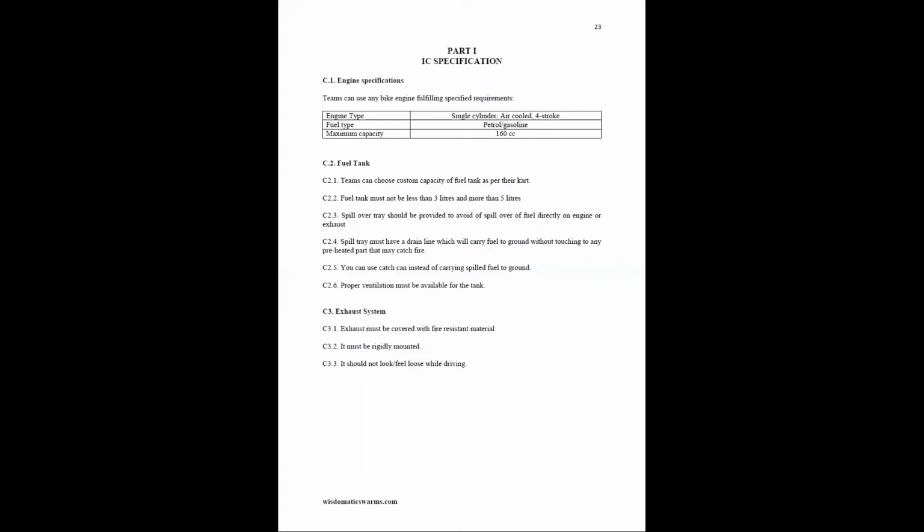Your exhaust must be covered with heat resistant material. It should be rigidly mounted. If the technical inspector finds your exhaust is not mounted properly, you won't be allowed for the further events.